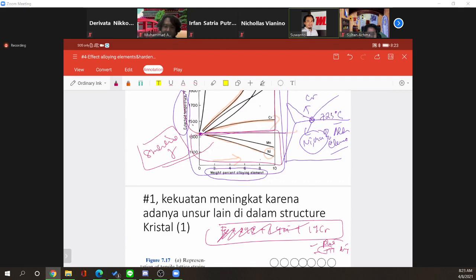The important point is that we would like to modify something, right? We would like to modify something, either keep it as austenite or make it martensite. The best way to see is that we look for the phase diagram for each alloy that we would like to transform into the microstructure that we would like. But our understanding about the effect of alloying is especially empirical.